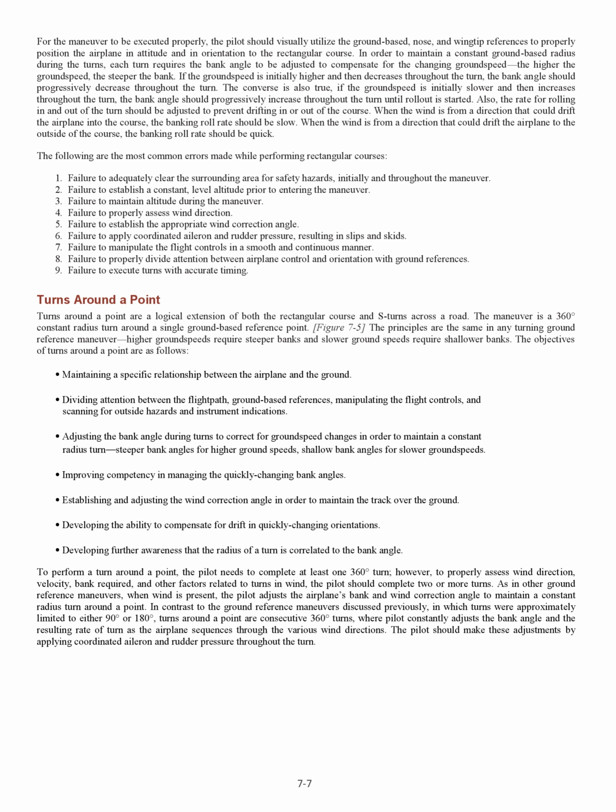To perform a turn around a point, the pilot needs to complete at least one 360 degrees turn. However, to properly assess wind direction, velocity, bank required, and other factors related to turns in wind, the pilot should complete 2 or more turns. As in other ground reference maneuvers, when wind is present, the pilot adjusts the airplane's bank and wind correction angle to maintain a constant radius turn around a point.